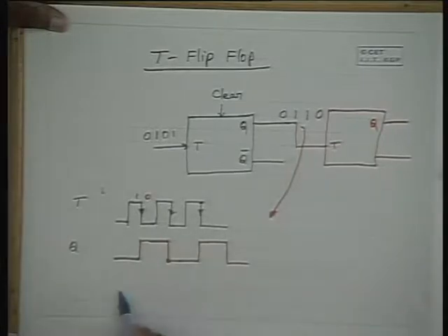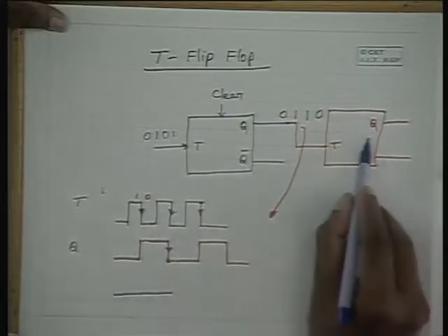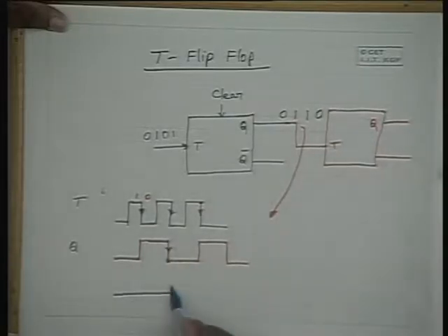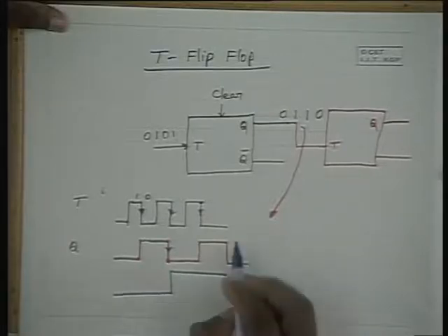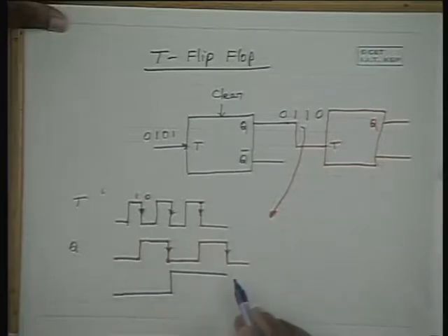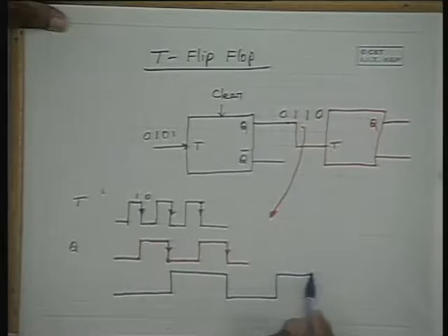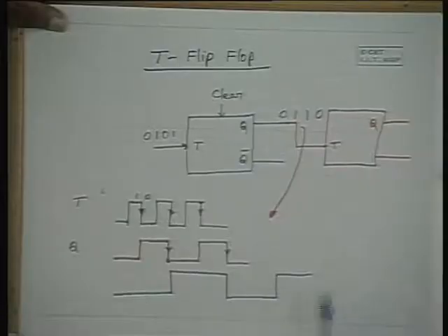If it is initially cleared, it would be a 0, and to this transition this second flip-flop responds, therefore it toggles to state 1 and it remains in the same state until this next negative transition occurs. So it will again toggle from 1 to 0 and so on. Hence the frequency gets divided further by 2, and if you have another flip-flop there, it will get further divided by 2, and that's how it can work like a dividing counter.